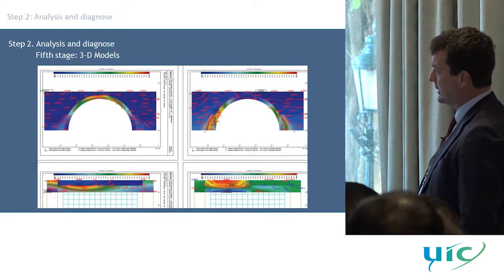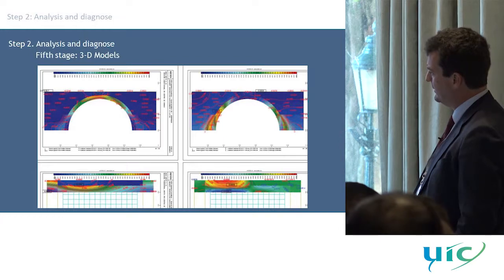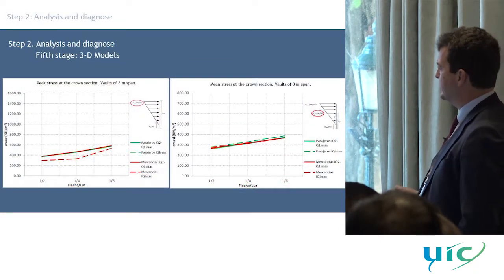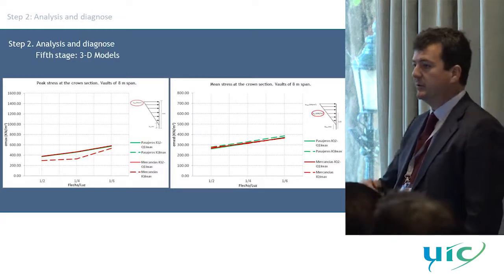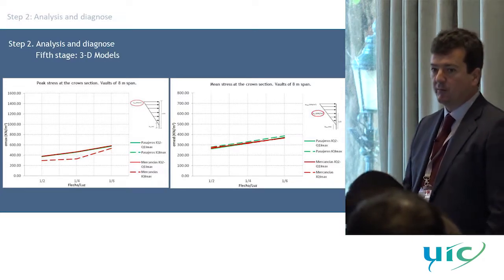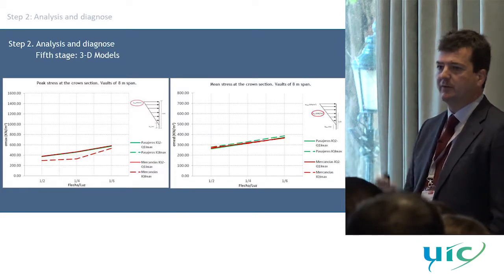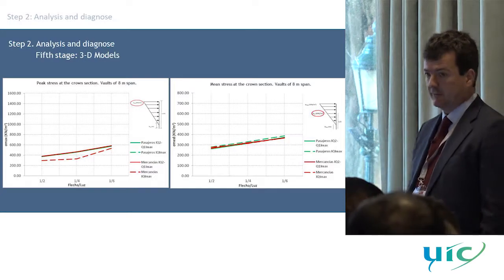In this case, we could analyze in some way the transversal behavior with a loaded track, only one. And again, we started looking for stresses, mean average stresses, peak stresses. Of course, in all of the cases, we have a reduced stress because the spandrels play a role not only as the stiffeners of the bridge, but also as elements that carry thrust. Okay?